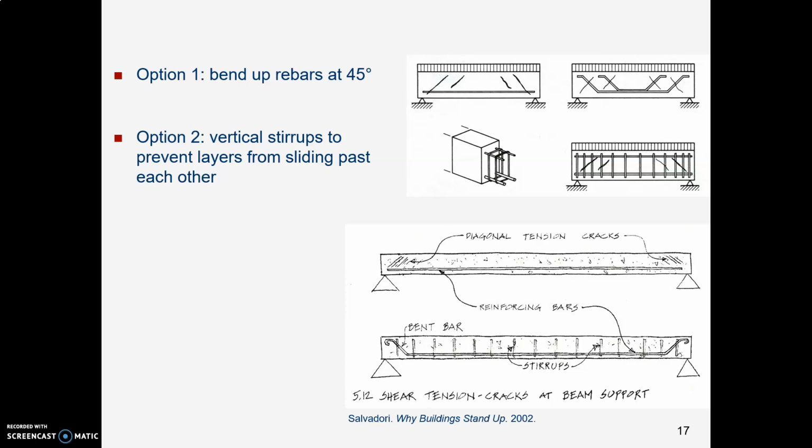Now think about last term when we looked at shear and moment diagrams. When we had a simple beam with a support at each end, do you remember how when the free body diagram jumped up, the shear diagram jumped up? It just jumped up suddenly, straight up. Lot of shear right here at that starting end.